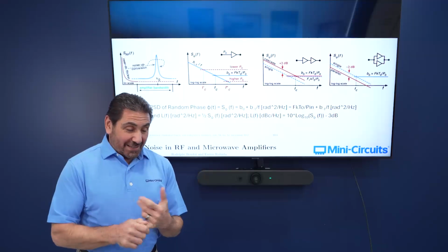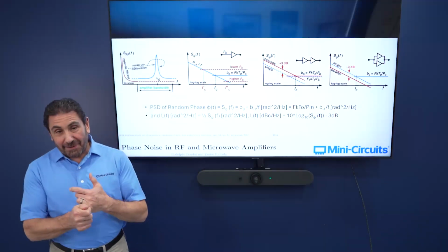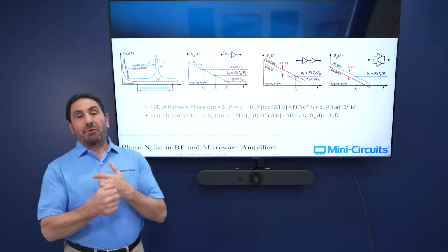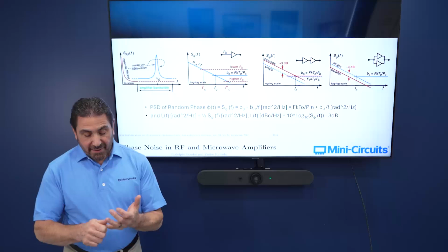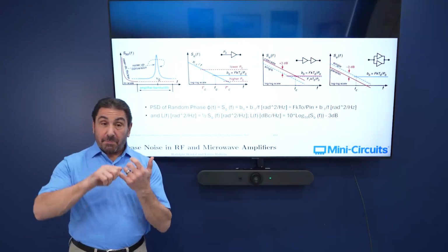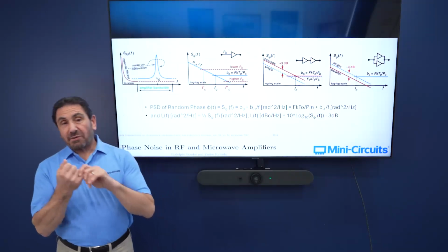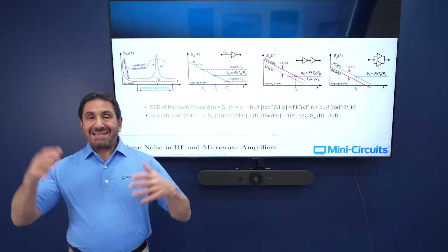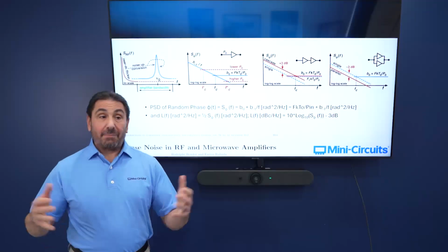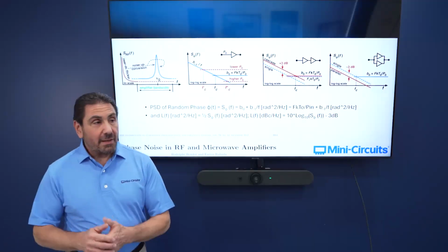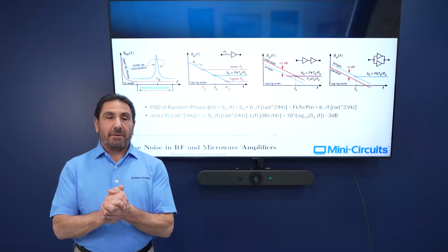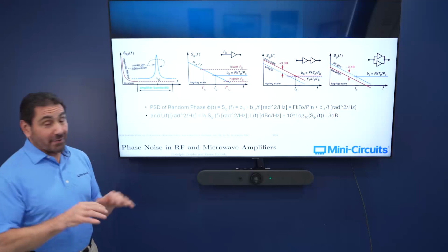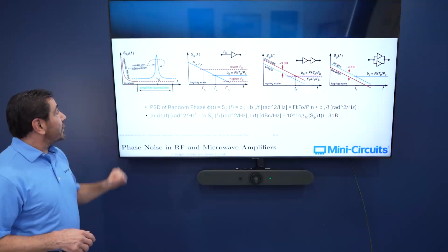That's because, unfortunately, pretty much every electronic component exhibits what's known as flicker noise, or 1/F noise. It's there in passive components, and it's certainly there in active components, and it definitely gets worse when there's a DC current applied. Well, amplifiers unfortunately need DC current, right? So the fact that you're biasing an amplifier and using active and passive components means you will generate, whether you like it or not, 1/F noise or flicker noise.